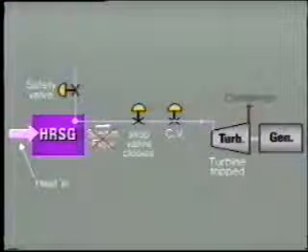The steam stop valve closes and the flow of steam is immediately halted, so that energy output from the HRSG falls to zero or close to zero. But we are still at this instance receiving heat input from the flow of exhaust gas through the HRSG. The result of this unbalance is that the steam pressure rises immediately and causes the safety valves to lift. In fact, if the safety valves did not lift, some components of steam piping and boiler tubing could be ruptured by the rapidly rising pressure.